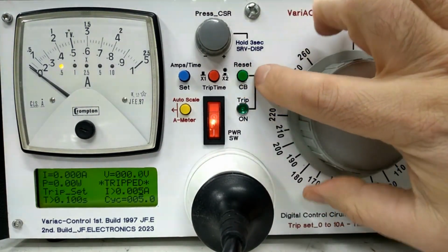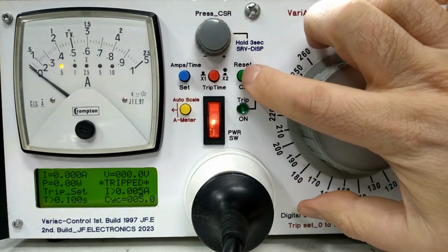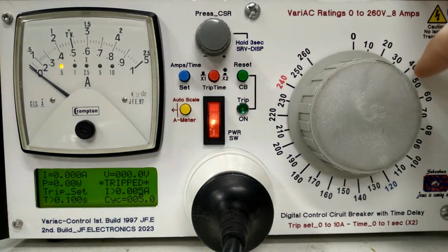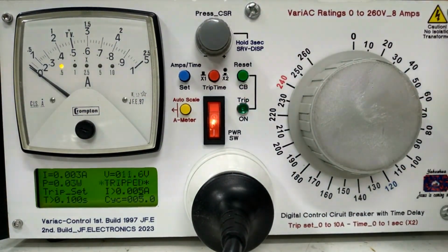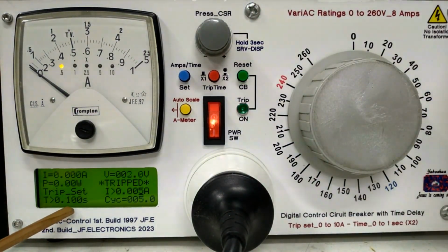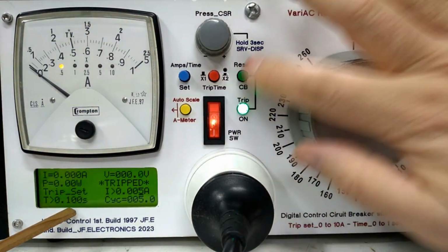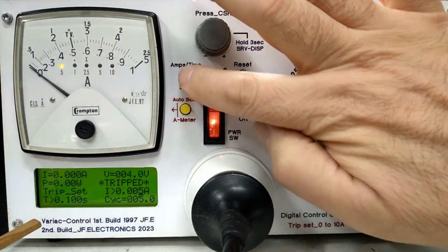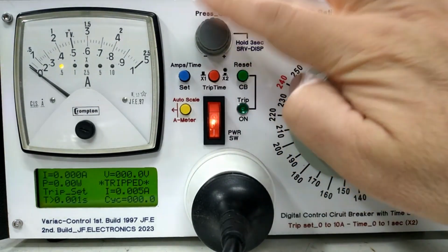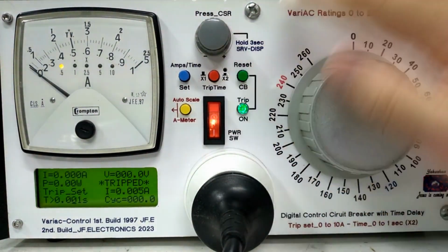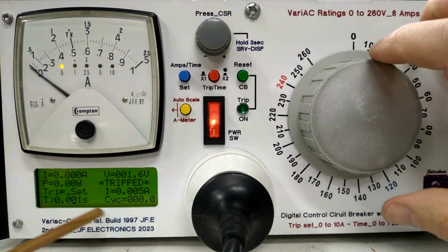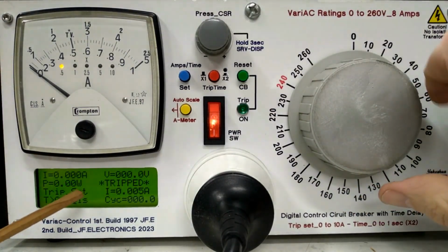So let's say if I press the trip setting, the reset, and I'm leaving the voltage with the load on and with the voltage where it was, we'll see what happens. And it trips, there you go. So it's tripping at 100 millisecond. Okay. So let's change the time delay. Now this should trip quicker. Well, it's probably because it's still trying to hit the limit.